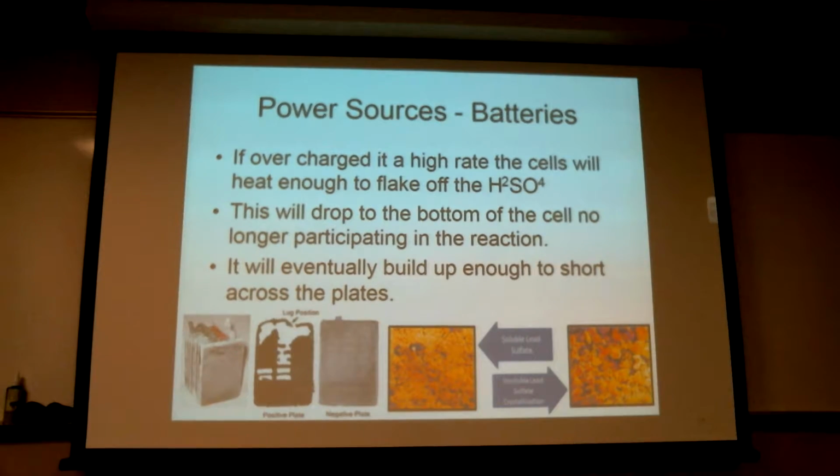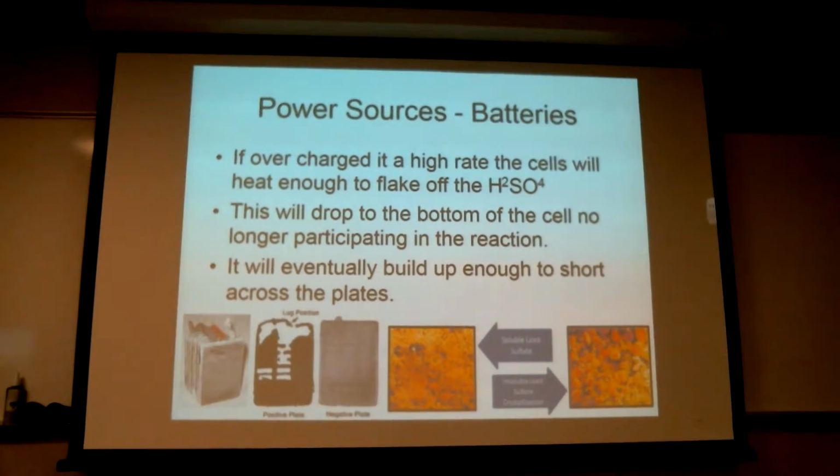Now, my experience with burp charging, particularly with an older dead battery, is you can rejuvenate them, but you can never bring them back to original capacity. I have not had the opportunity to play around with taking a new battery and using it in a normal cycle, and then maybe every 3 months burp charging it for a day or two, just putting it on the trickle and burp charging it for a day or two, and then see if I can get 8 or 9 years out of the battery that way, rather than 5 or 6 years.